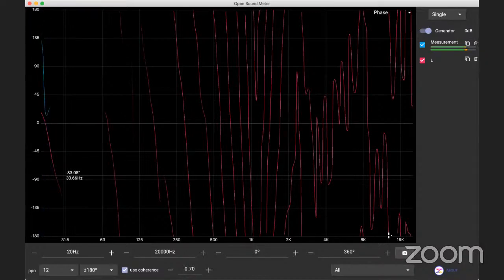So it doesn't matter which frequency you're measuring; what matters is where you are measuring it and what is the reason for you to measure it. That's what you need to understand. If you're measuring in live sound, you will measure A-weighted and C-weighted, because when you measure only A-weighted, it is not calculating the sound waves coming out of the subwoofer properly. So to measure that, you need to move into C-weighted.